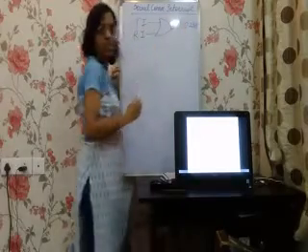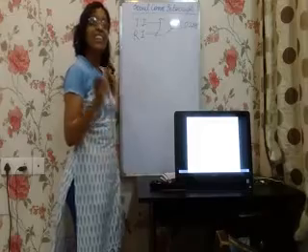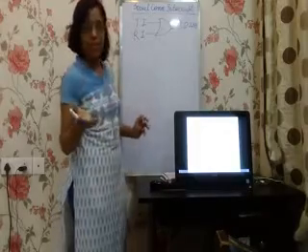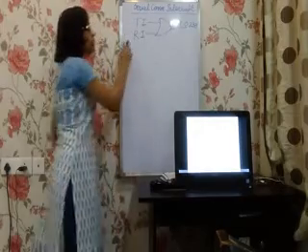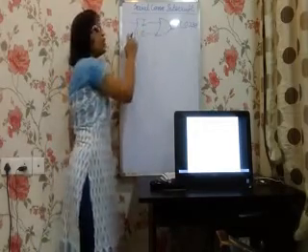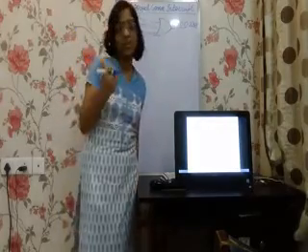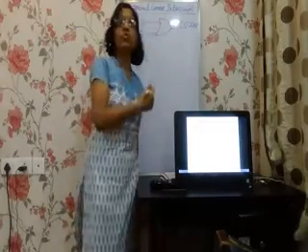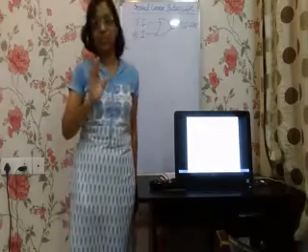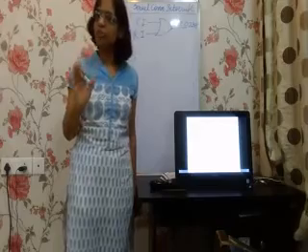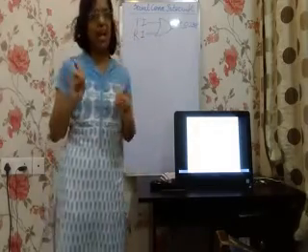Whenever we are writing a program in which serial communication has to take place along with some other function, we use the interrupt method. We check both these flags because there is only one interrupt for both transmitting as well as receiving. We need to know which of them caused the interrupt. Once we know that, we can program accordingly. So this much knowledge you should have before we start with the program.